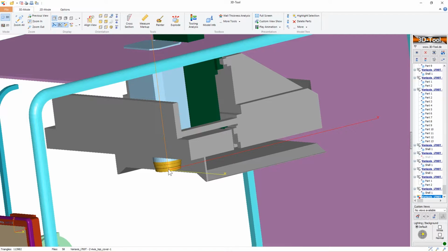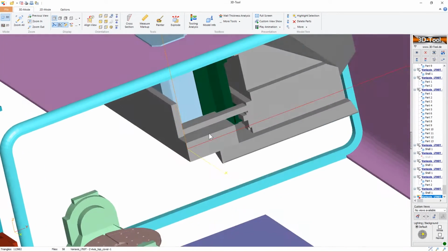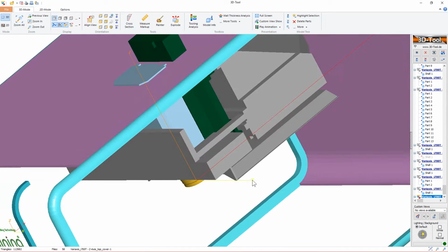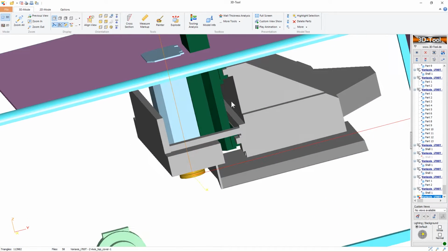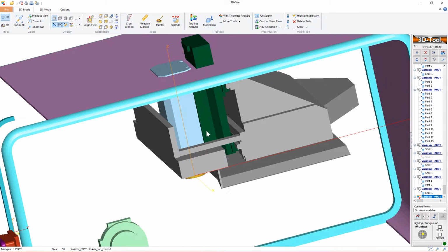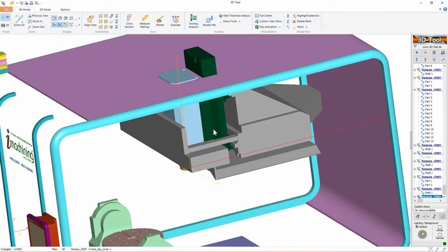So the first linear axis is located on the spindle, and therefore it can move along the y-axis. The next one, the green geometry, represents the x-axis, as you can see with this yellow vector. And the third axis is the z-axis, and it's located over here. It's very important to follow the rules of which axis is first, and which axes are the child of the previous axis itself.